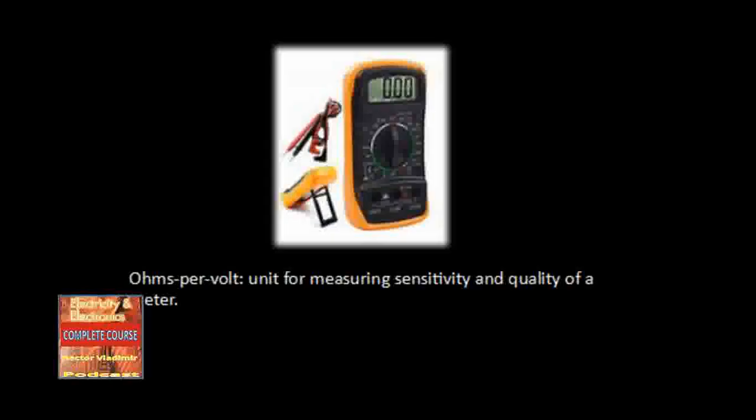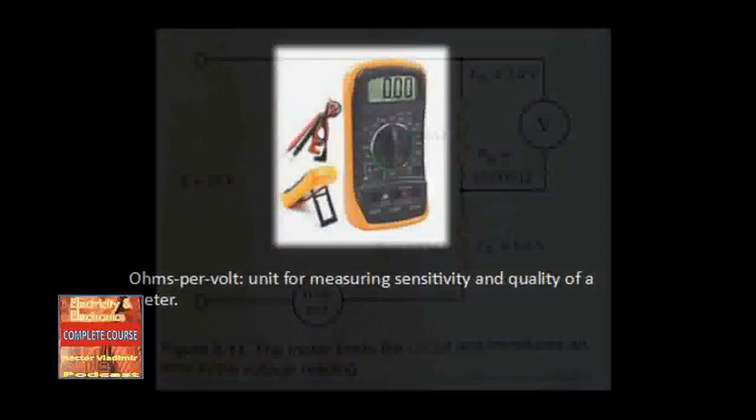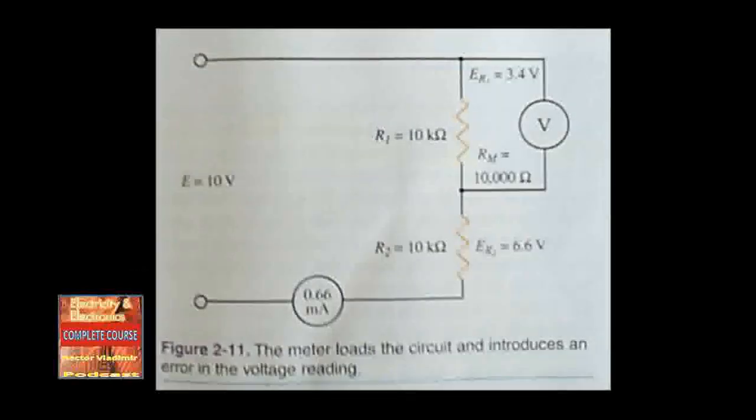Accuracy of the meter is commonly expressed as a percentage, such as 1%. That means that the true value will be within 1% of the scale reading. Another system of rating meters is the accuracy expressed as a percentage of full-scale reading. A meter may have a rating of plus or minus 0.05% or less. In general, the smaller the percentage, the higher the quality of the meter.